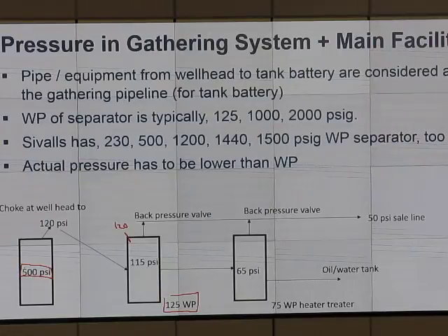When you have pressure from the well at 500 psi, you will ask how long will that produce at a quick rate? Will it be 3 months, 2 weeks, or 5 months, 6 months? So what you can do is close the well a little bit, and you set it at 120.